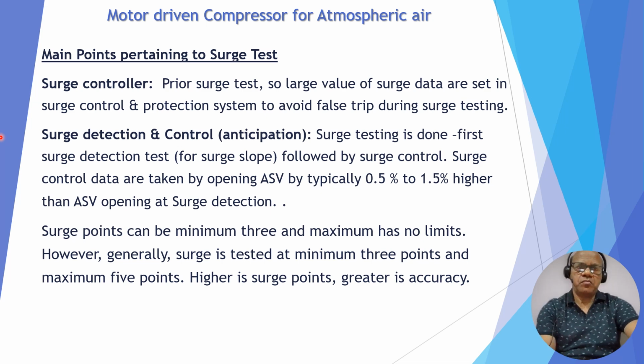Surge controller. Since the machine is not yet surge tested, we cannot use the actual surge control. So large values of surge data are set in the surge control and protection system to avoid a false trip during the surge testing.